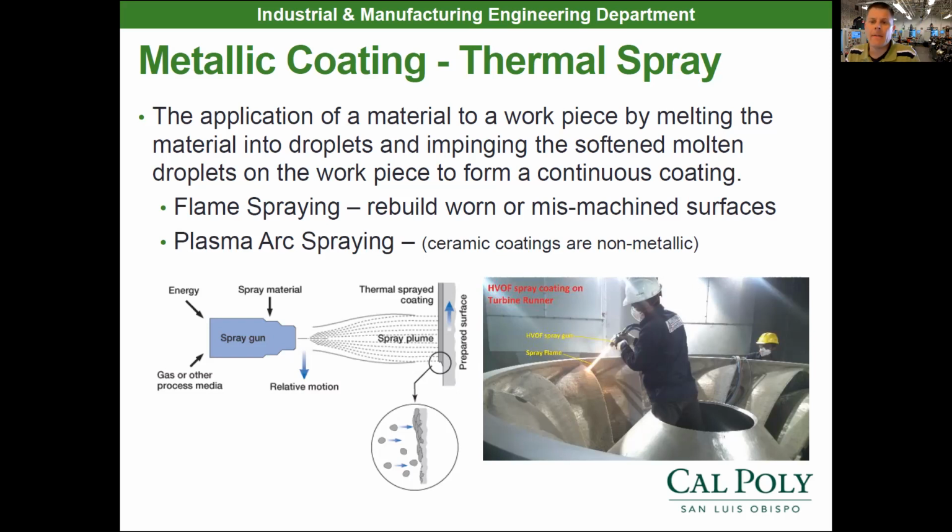Now, in the case of ceramic coatings, sometimes people put ceramic coatings on top of things to alter the properties of the headers. For example, you can keep heat in with a ceramic coating on your headers. The hotter you keep your exhaust manifold, the faster the gases are going to travel through there, right? So sometimes it's good to have hot exhaust manifolds. And sometimes you ceramic coat them in order to keep that heat in there.